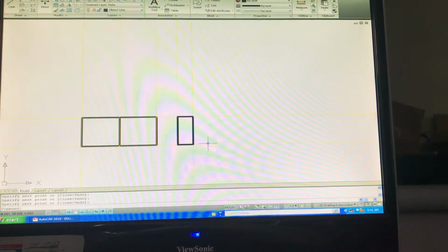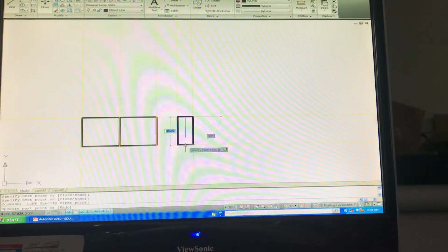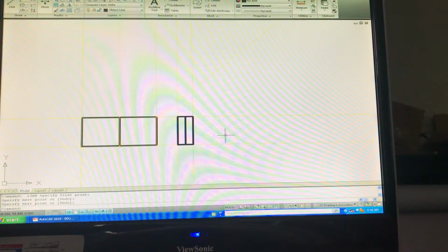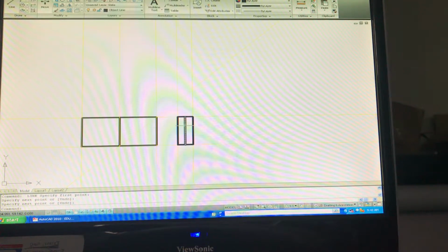Now again, I know that my half lap is half this distance, so I can go just from midpoint to midpoint. How long is the width of that? What is the width of that for the short line of bar? This one? That one up there, yeah. It should be 3/4 of an inch. We should have that construction line, so we should just be able to snap right to it.